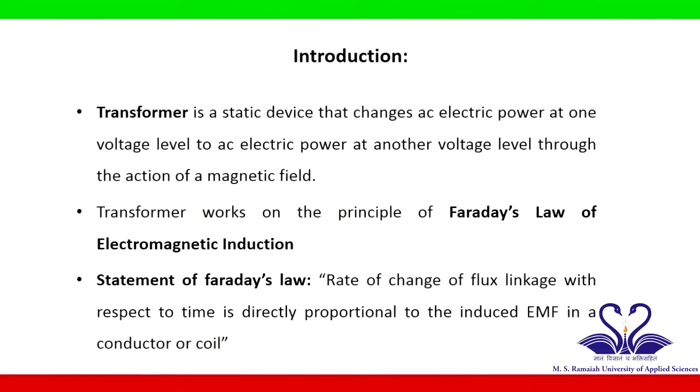Introduction. Transformer is a static device that changes AC electric power at one voltage level to AC electric power at another voltage level through the action of a magnetic field. Transformer works on the principle of Faraday's laws of electromagnetic induction. According to the statement of Faraday's law, rate of change of flux linkage with respect to time is directly proportional to the induced EMF in a conductor or coil.